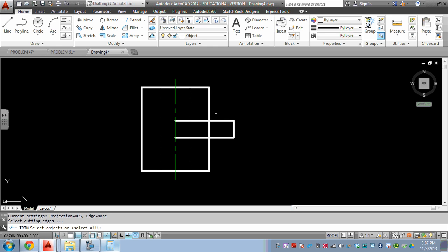Also, there is actually no hidden line right here because it goes right through and it wraps around. So this is formed right around this tab here. So when we put this in, I'm going to offset this 0.75. Yeah, there. That 0.75 has to be from the edge of here. 1.75 from the edge this way.